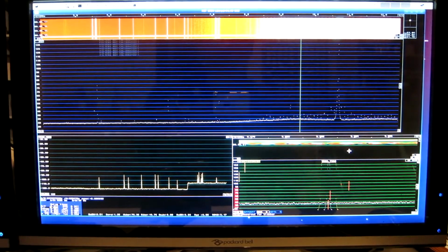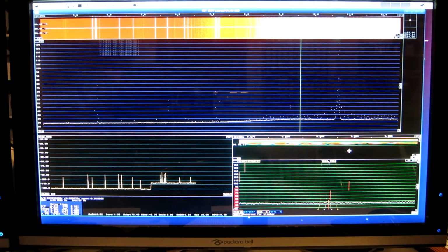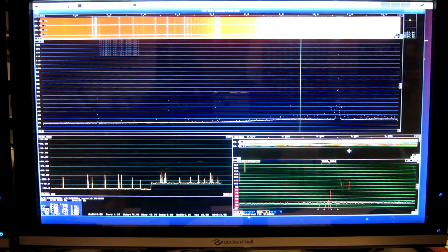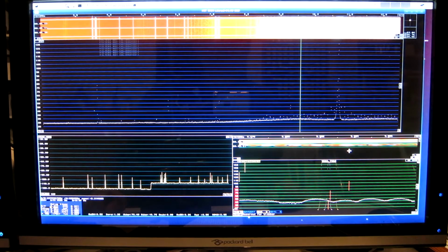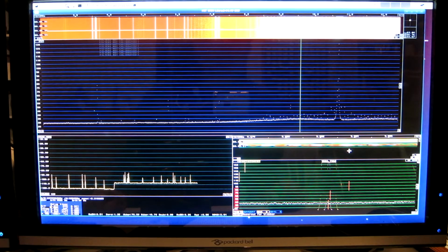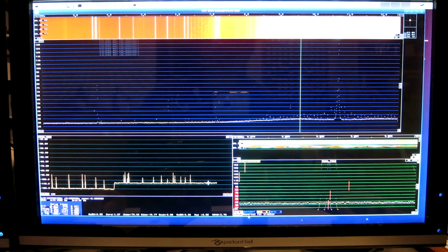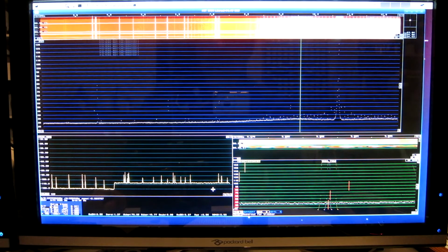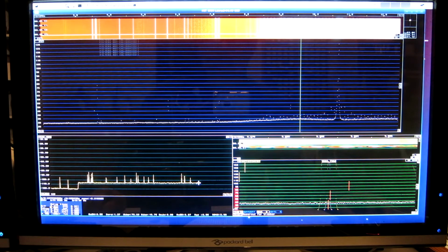The signal generator is not bad at all. It's a low noise machine, but compared to modern digital technology, it isn't really very low noise. You can see here 1 megahertz away, the noise is about 14 or maybe 13 dB above what we had from the signal from the crystal oscillator.